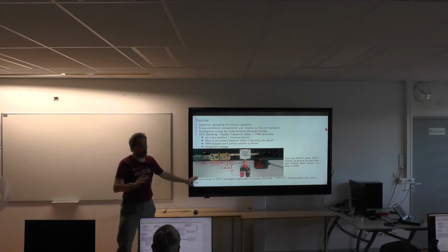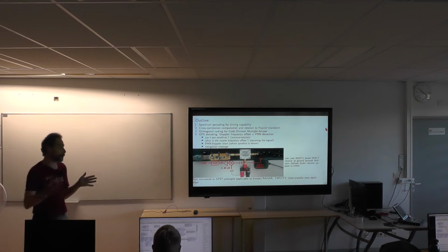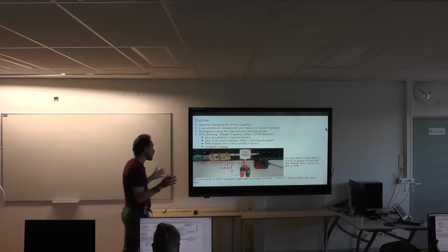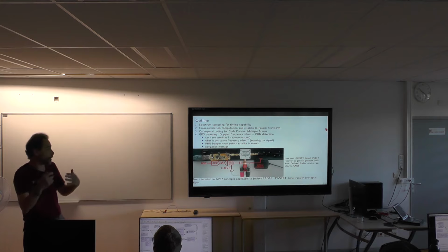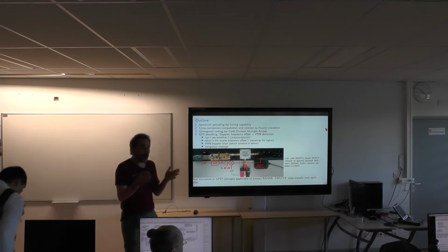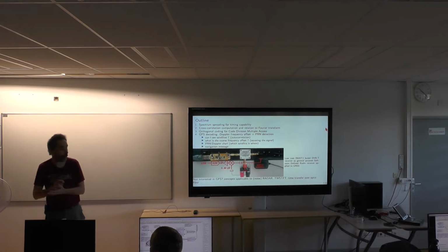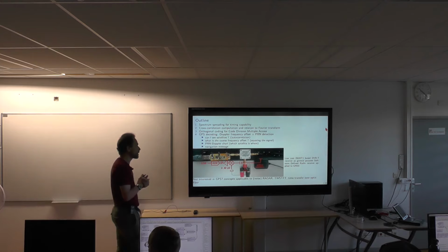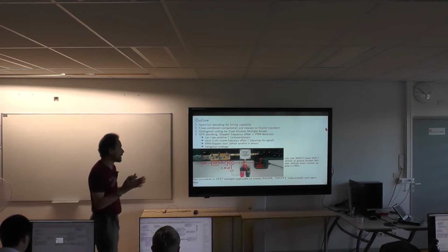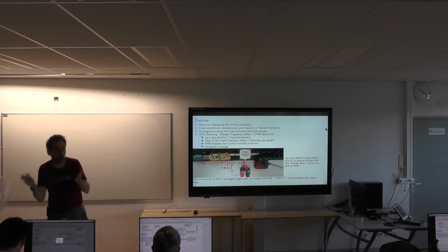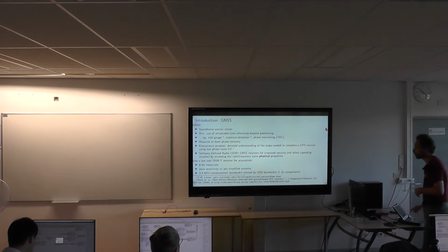And just to raise your interest, if you don't care about GPS, what I'm going to tell you about is applicable to any time transfer technology, whether we're talking about radar, because when you want to detect a target, you're ranging between your emitter, target, and receiver. It's exactly the same story. We're using the same technology for two-way satellite time and frequency transfer. So we developed a software-defined radio modem for broadcasting time over geostationary satellite. It's also applicable over optical fibers. You can modulate your optical wave the same way you're doing this with microwave signals. So the story I'm going to tell you here is applicable to most media for transferring time.